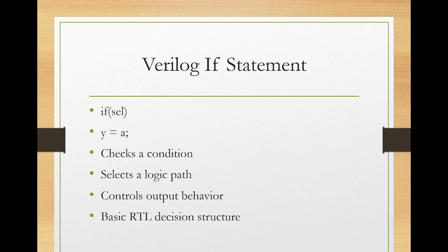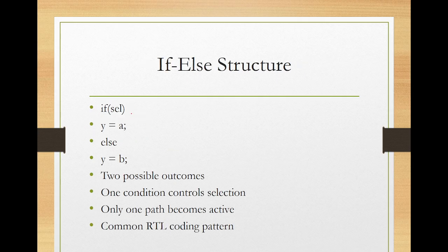Now let's meet the star of today's video. if (sel) y = a; looks simple, looks familiar, looks exactly like programming. And that's where beginners get trapped, because Verilog isn't programming, it's hardware description. This if statement isn't an instruction, it's a hardware blueprint.